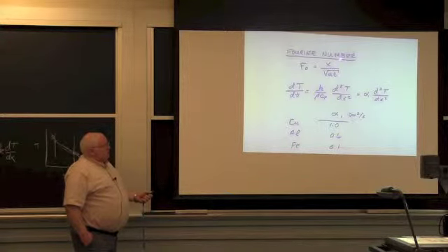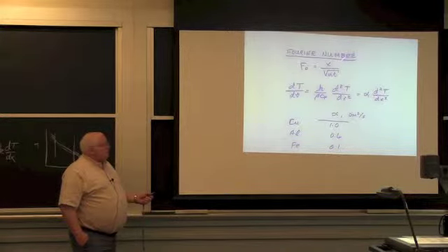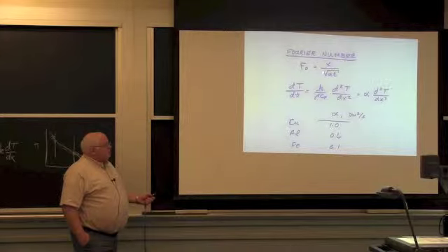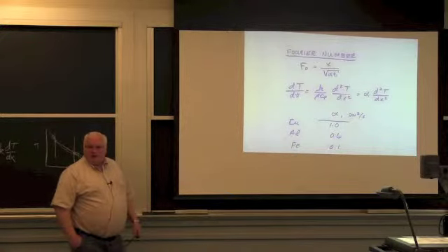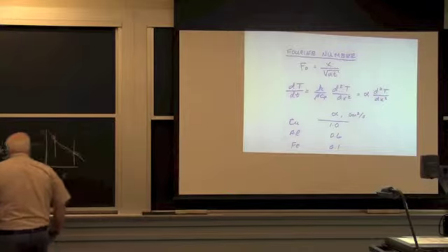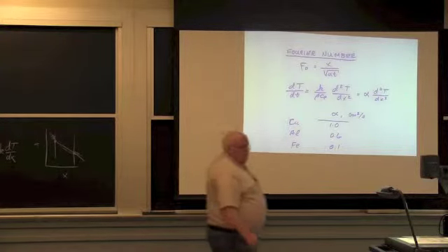If we're talking about mass diffusion, it's called the Fick number, and it's x over the square root of Dt, where D is mass diffusivity, as opposed to alpha, where alpha is thermal diffusivity. Alpha has units, oh here it is, I got it already, of centimeters squared per second.